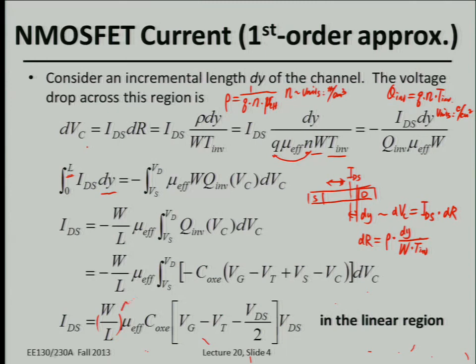Okay, so basically, it only tells you that it only depends on the ratio of channel width versus gate length, right? So this itself proves that the MOSFET is a surface device, right? It's quite different compared with the devices you learned previously, like the Schottky diode as well as the PN diode, in which once you calculate the absolute current, you should use the current density times the cross-sectional area. But for the MOSFET itself, it seems to be only proportional to that ratio.